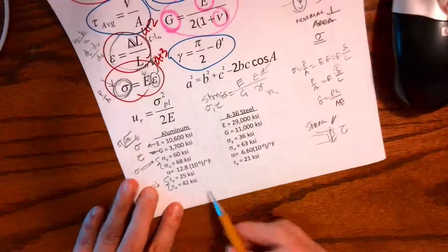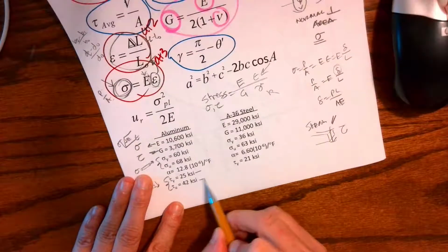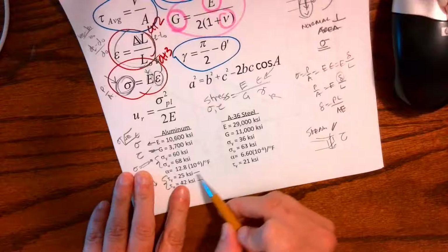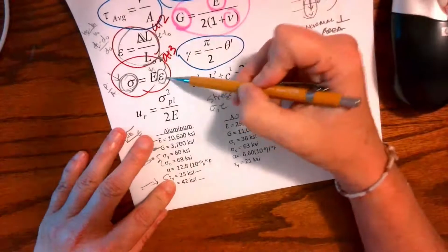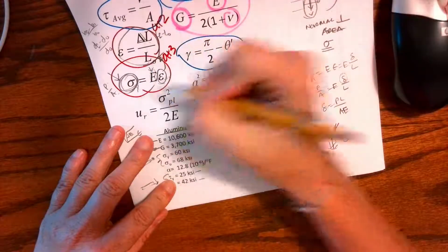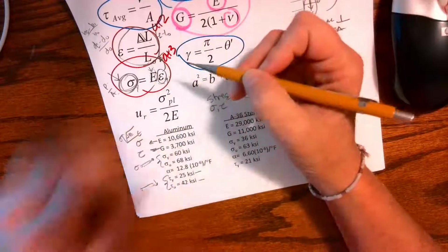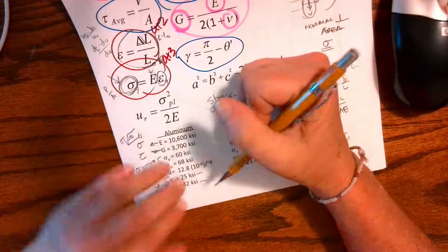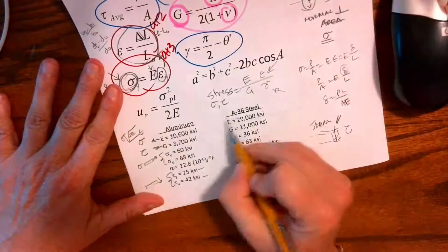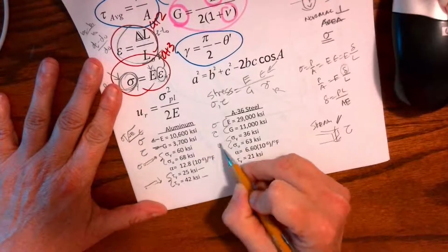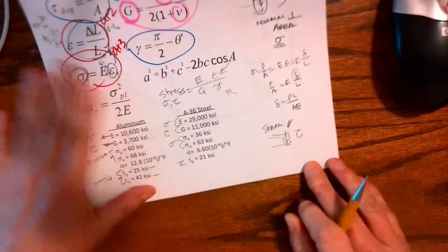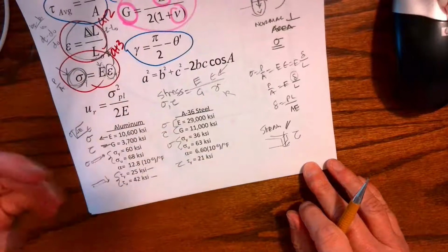Okay? You need to know the difference between yielding and ultimate. Yielding is when we're still in that elastic region. So when I use this equation, I'm really looking at yield stress and yield strain are smaller. Okay, ultimate, so we'll talk about these in more detail. This goes with normal, this goes with shear, this goes with normal, this goes with shear. Okay, so you have to understand what you're pulling.